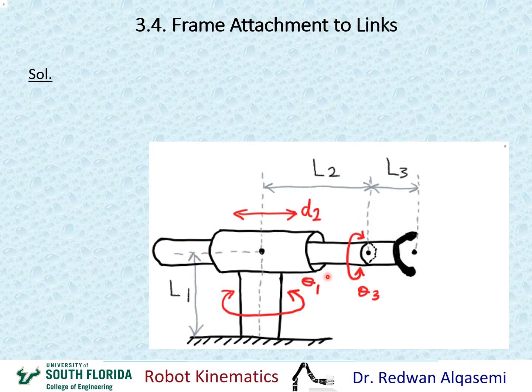Okay, so I'm going to start now with the z-axis, z1. Z1 is the axis of motion for the first joint. Since I have a revolute joint, this is the revolute joint here, it rotates in this direction. And the axis of rotation is this axis that we see here, the dotted line. So that means this axis would be my Z1 axis.